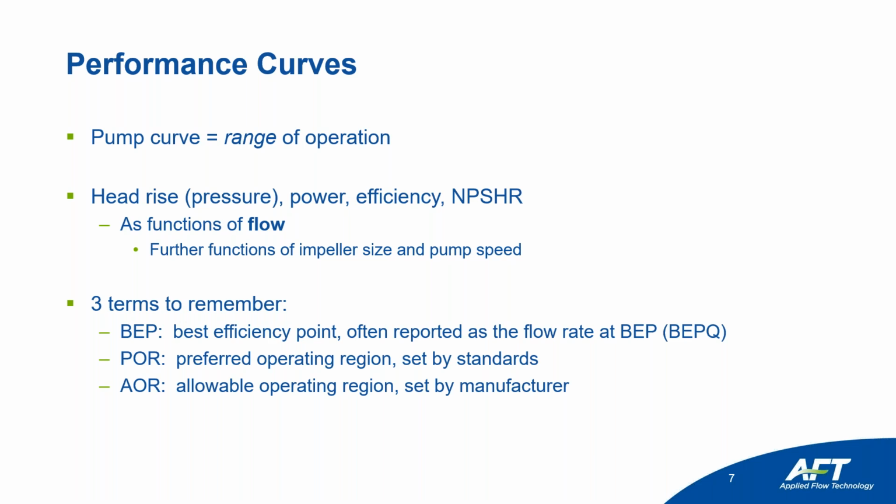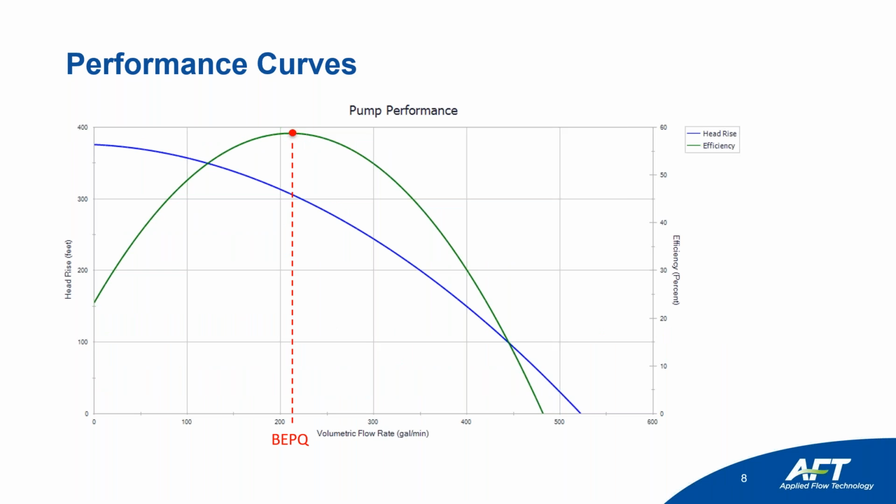This is going to be easier shown, of course, with a graph because we want to look at a pump curve. So here's an example of a pump curve in Fathom. We've used a curve fit, so it's all smooth and all that. And we'll see you don't always have to do a curve fit. In fact, we won't in my examples. But this is to show you what the BEP is. So you have your efficiency curve. What this means is that different flow rates are going to, and this is totally dependent on the pump, every pump is different, at the point of maximum efficiency, that is what is known as the best efficiency point. It is a single point on the curve.